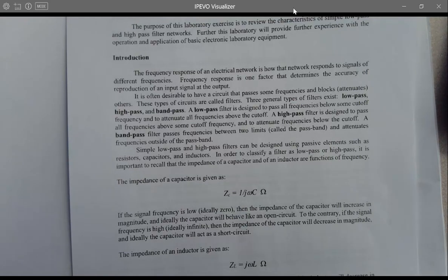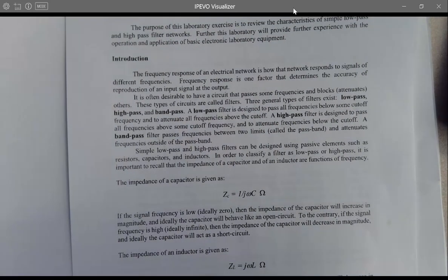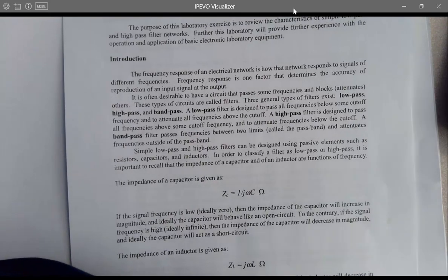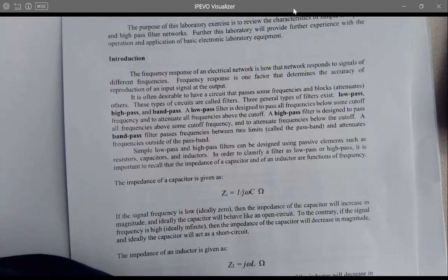So the AC coupling removes the line, which is the DC part of it, and only shows the varying signal, okay? Even though it's probably more complicated than the filter itself. But if you do AC coupling, what component is being filtered out? If you press AC coupling, it removes the DC offset, right?